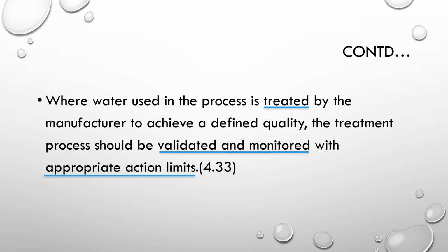But before the validation of the water system, it has to be qualified. The qualifications should include comprehensive design qualification, installation qualification, operation qualification and performance qualification. The design should provide a suitable stainless steel, maybe SS316L tank for storage of water, suitable orbital welded piping, necessary slopes, sanitary valves, tri-clover valves, etc. These have to be looked into carefully.